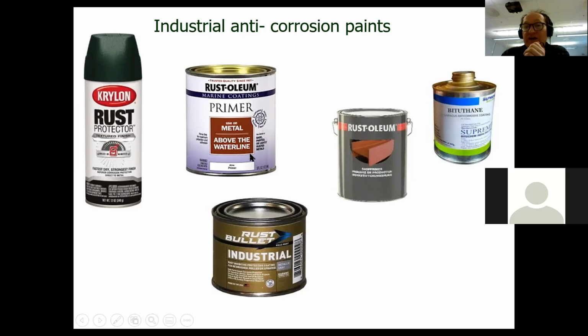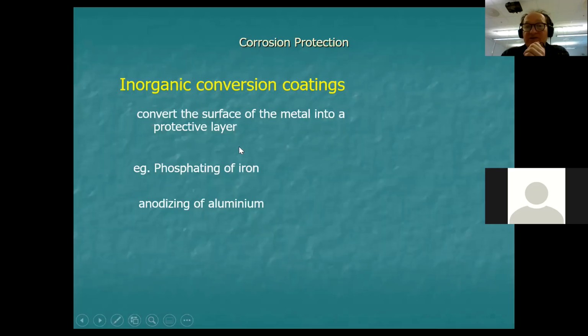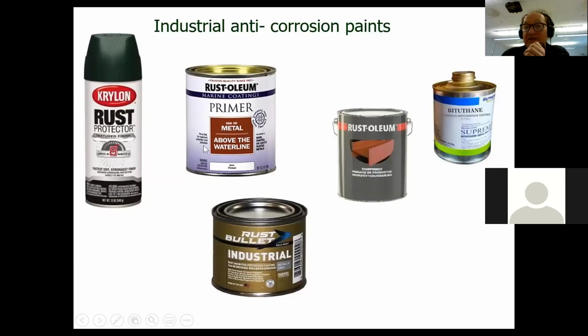First of all, it may contain materials such as, if I go back here, this phosphating compound, for example, in the primer itself. Normally that is the case. So you put the primer on to protect the metal with, let's say, a phosphate coating. And then it also provides a good surface for the main paint film to stick to. So instead of the main film sticking to the metal directly, it sticks or is adhered to the primer.